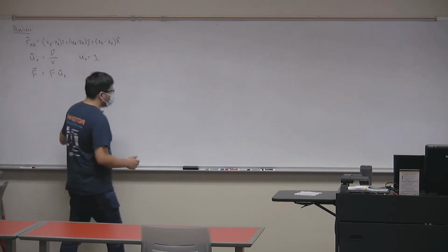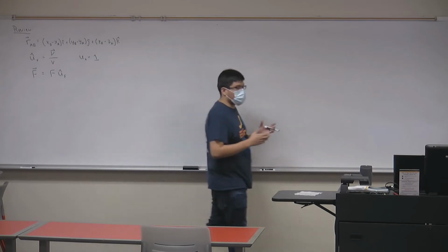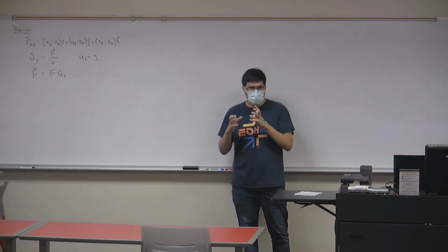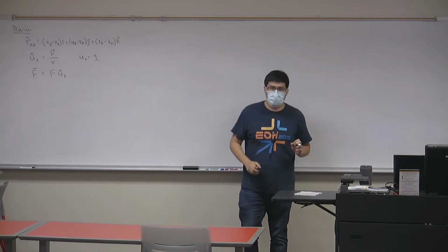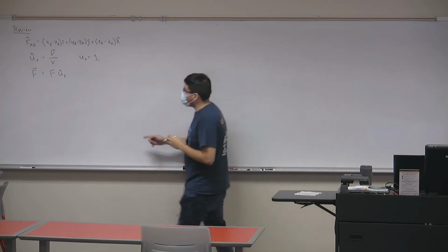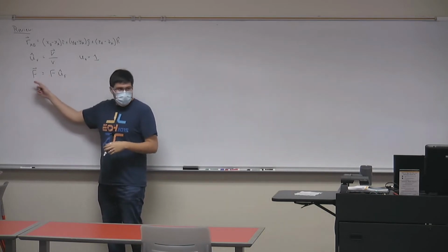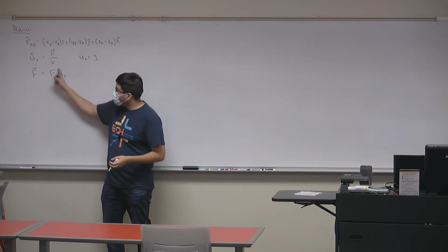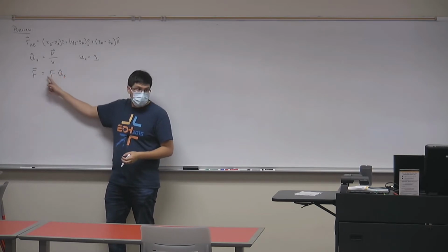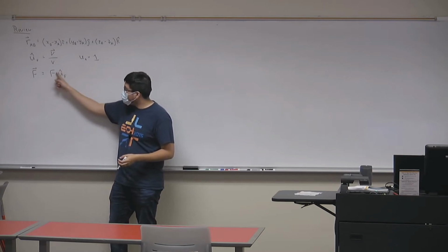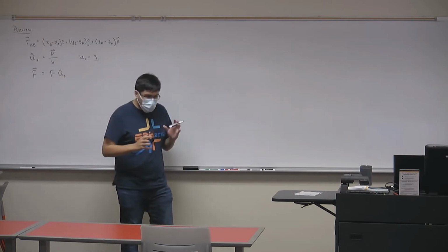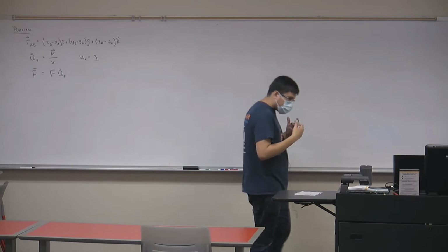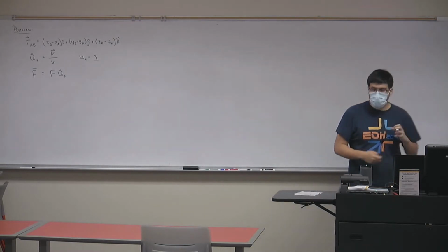And I did make a note about trying to visualize vectors as products between a scalar quantity and a directional quantity. So for example, this force vector, instead of just looking at fx, fy, fz, I want you to visualize it as the product of one scalar, this magnitude, times a unit vector. This is going to help us when it comes to doing vector operations.